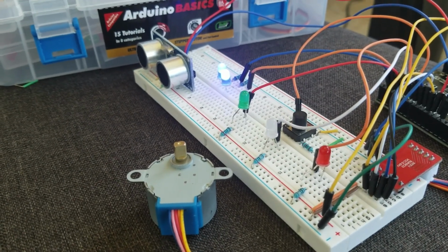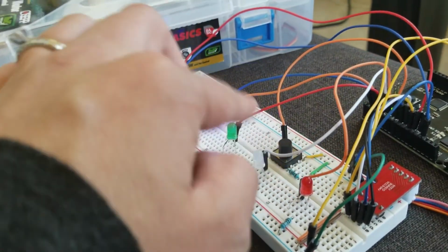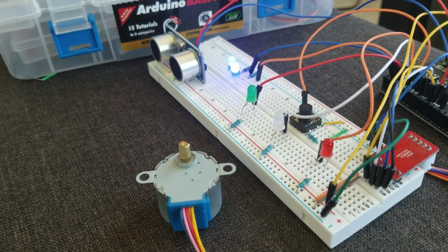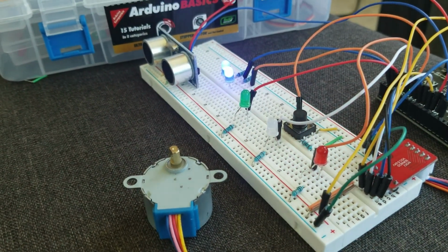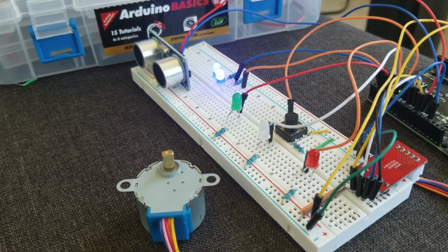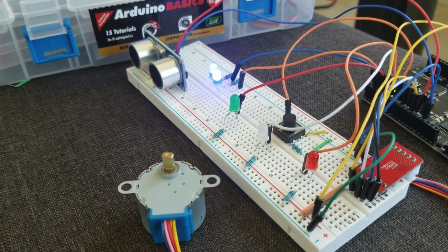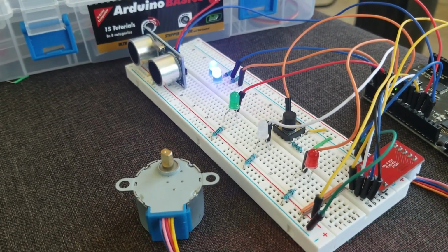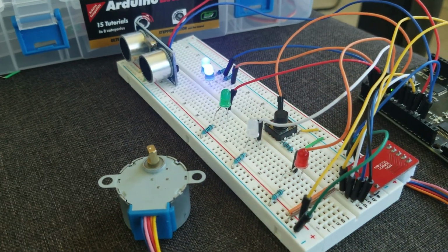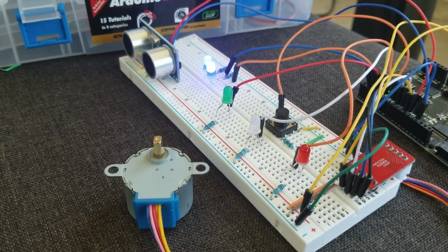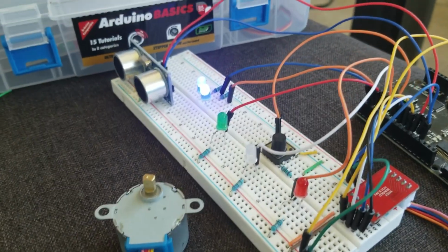So I have 3 functions, 1 for each station, 1, 2, 3, and then a 4th function, which is what's running this stepper motor. So again, I used the code that I found in that 4th function. And then there's a tricky little piece of programming that tells the program to do something if the number is odd or even, so I have it counting the parts that are traveling along my assembly line, and if it's an even numbered part, the second LED lights up. And you can see that in my serial monitor here.